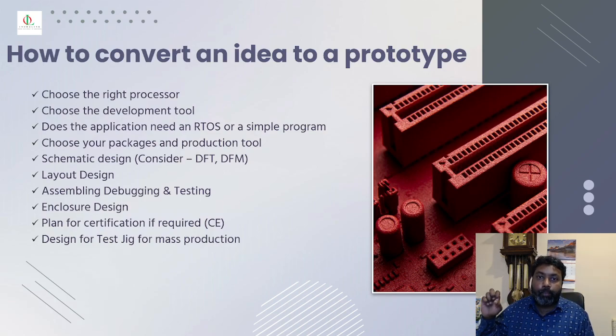But again, being a design engineer, it's your responsibility to choose those two as the main before you jump into the real project itself. Then the third one is, does the application need an RTOS, a real-time operating system, or just a simple program which can be run with a simple infinite loop if it's for small applications? You need to decide that.